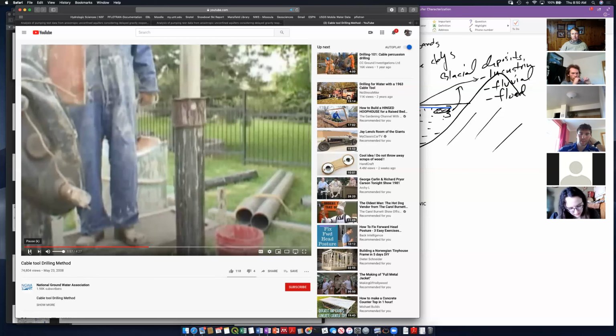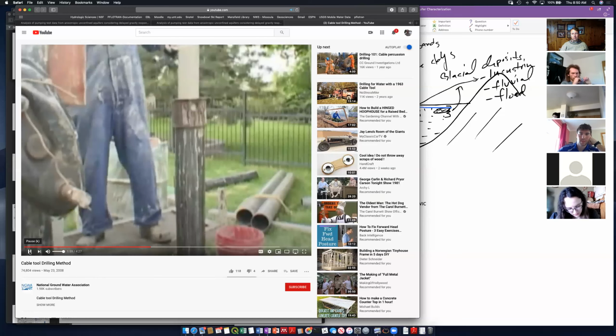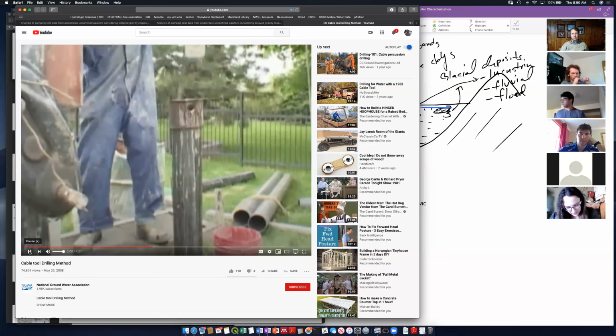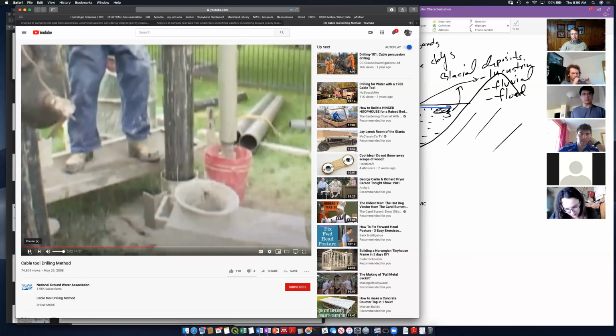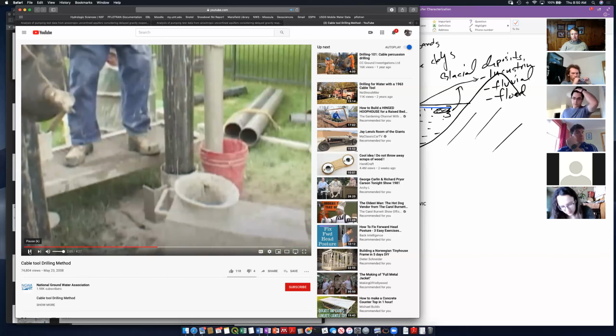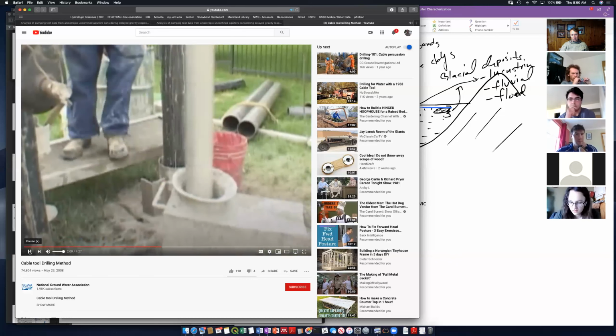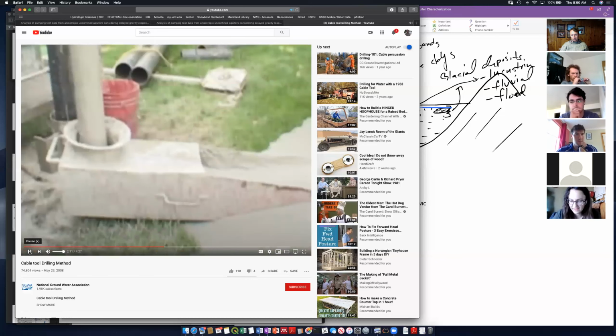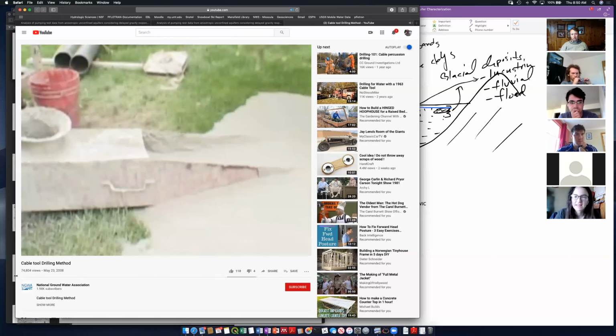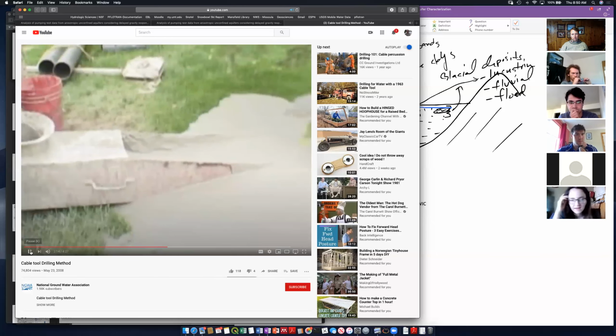The bailer is simply a hollow tube with a check valve on the bottom, which fills with the cutting slurry mixture. The action of the dart valve enables the bailer to collect cuttings for ID and recording purposes, as per Regulation 903, as well as removing accumulating cuttings by dumping them in the mud spout.